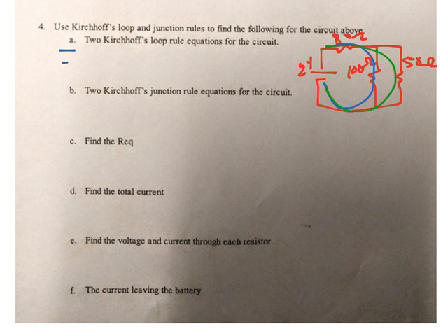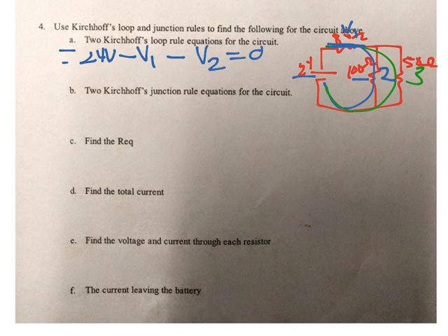In our first loop, we start with our 24 volts, the initial. Subtract your first voltage. I'm going to call this area 1 and 2, and call this one 3. So subtract the volts from 1, which is right here, subtract the volts from 2, which is right here, and this must equal 0. Then for my second loop, again we start with 24 volts minus your first, it goes around, and now hits over here, which we called 3, and this must equal 0.